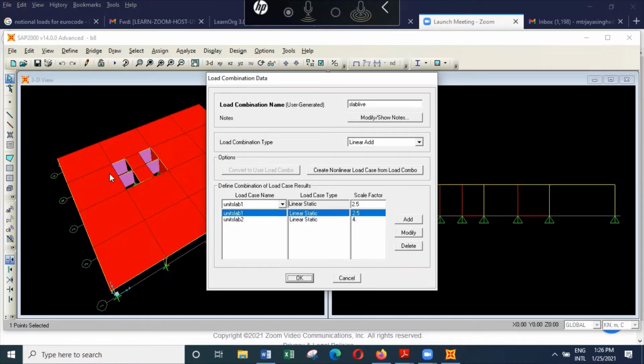And because we have defined each for a particular case, when you want to consider different types of loads that will be acting, including the self-weight, you can define these as combinations. These combinations will help you to increase the load to the level that you need from a unit load. So we start with the unit load and then we enhance it to the actual load condition.